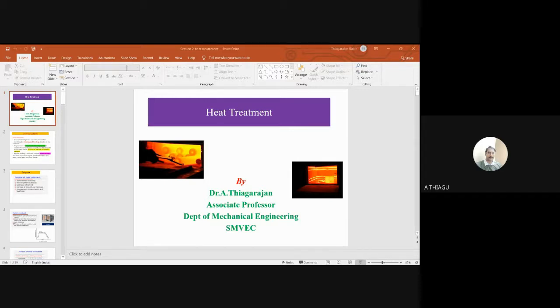This is the case where we do the cooling process. Parallelly we have a setup of quenching medium, so water is allowed to cool the sample. That's why we have provided the provision. Practically there are a lot of applications of the induction hardening process. The only thing is the time consumption is very less and uniformity of hardening is possible. That is quite interesting.